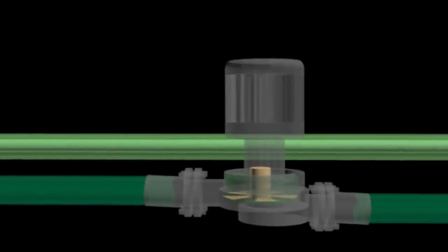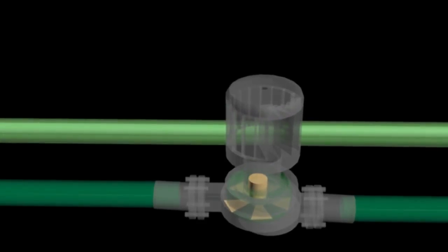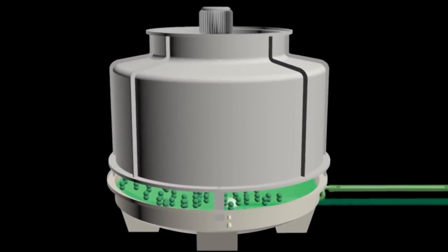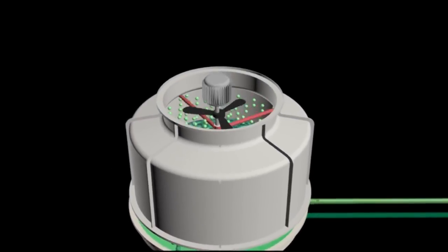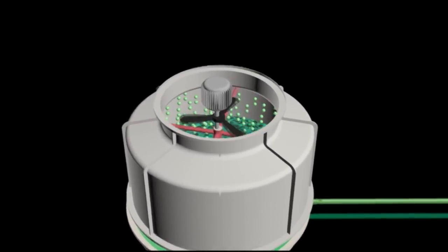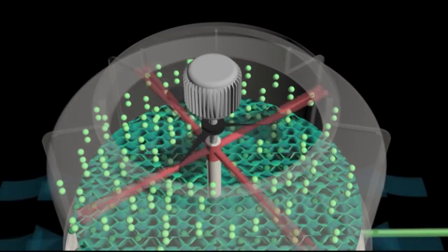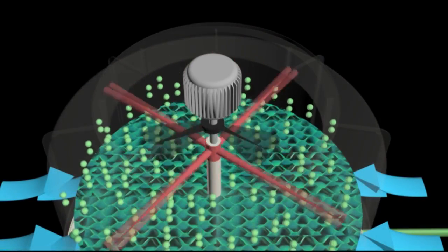From the condenser in the chiller, condenser water flows to the cooling tower with the help of a centrifugal pump. This water is called condenser water return. The condenser water will pass through the rotating sprinkler blades on the cooling tower. These rotating blades use pressure generated by the condenser water itself. Water will gush down through the fins to reduce the speed of the water going down.